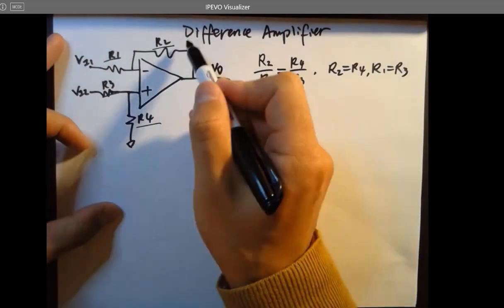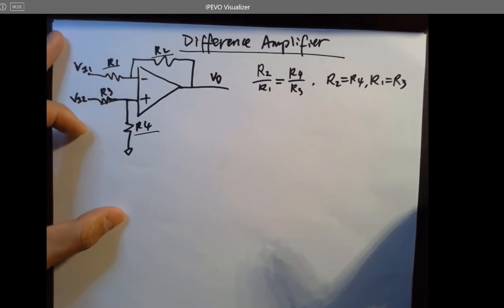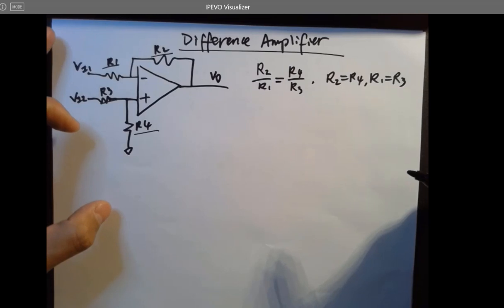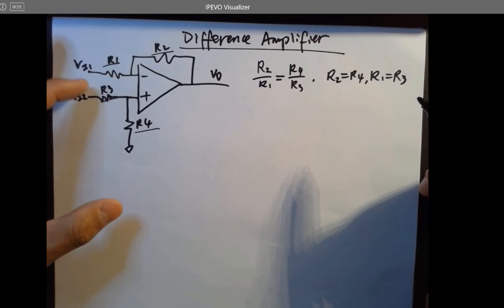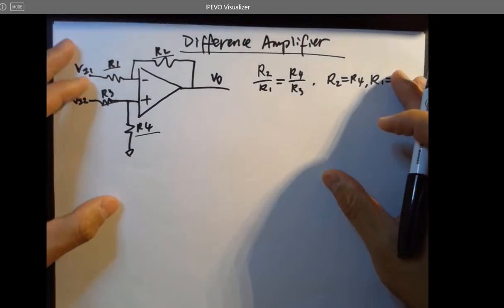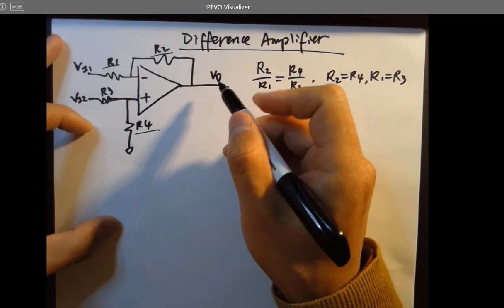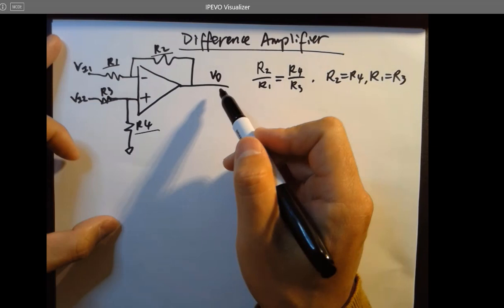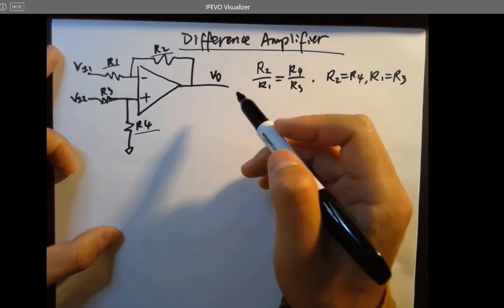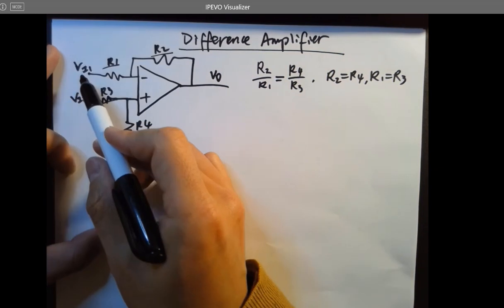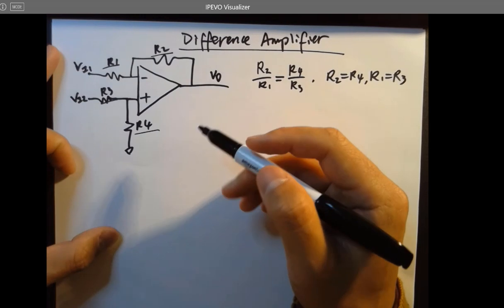So there are two different voltage gains to evaluate the performance of the amplifier. The first one is called the differential gain. That's the gain we are trying to derive first. Since there are two different voltages contributing to VO, we can use the superposition method: apply one voltage at a time and then superimpose them afterwards to get the overall VO.